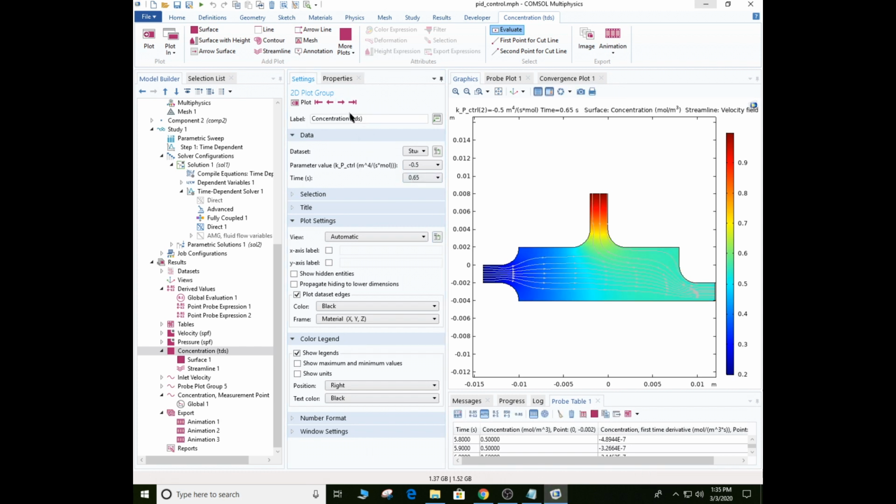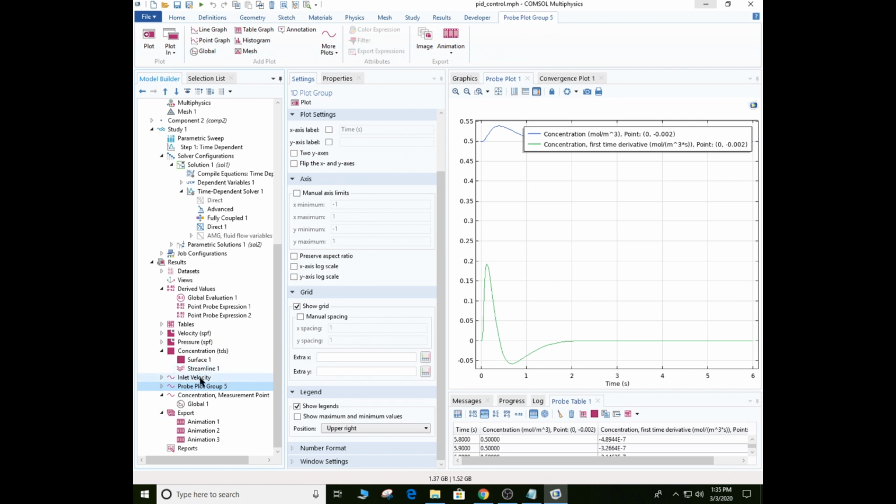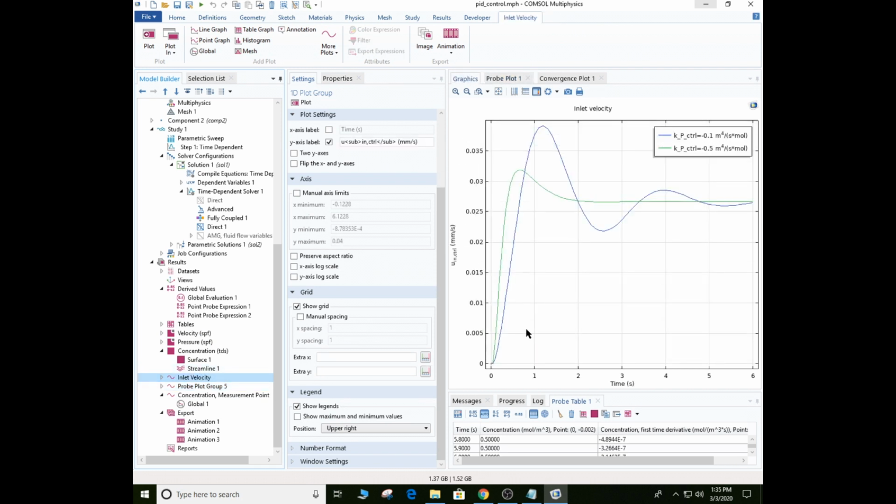Okay, and so again, that's how to do that part right there. So now, if we want to look at this inlet velocity right here, remember we had 2 types of values for KP, and that's the proportional controller. We didn't change these at all. We kept those steady, right? I think that was like at -1, and that was like -1e-3, something like that. But this is the one we're modifying right there.